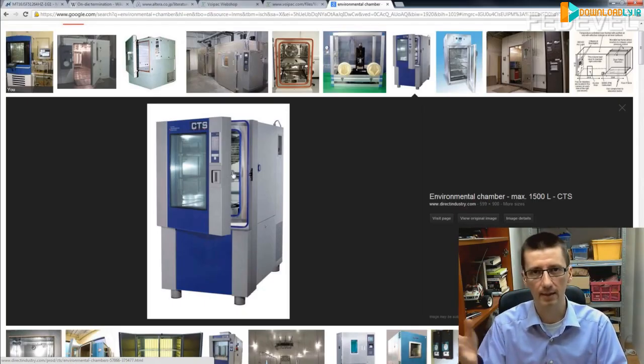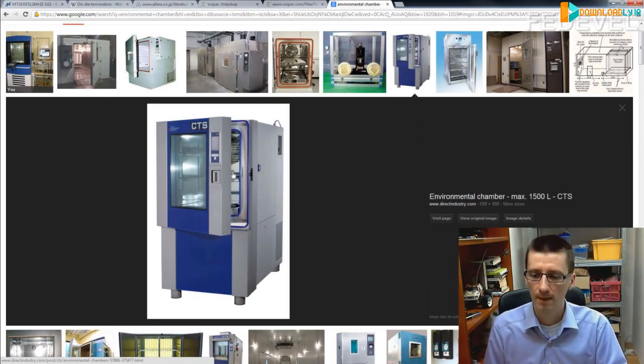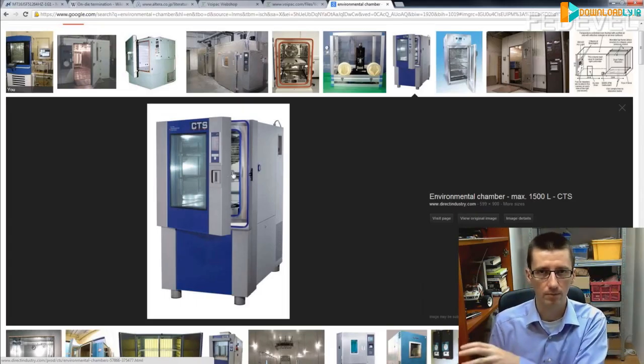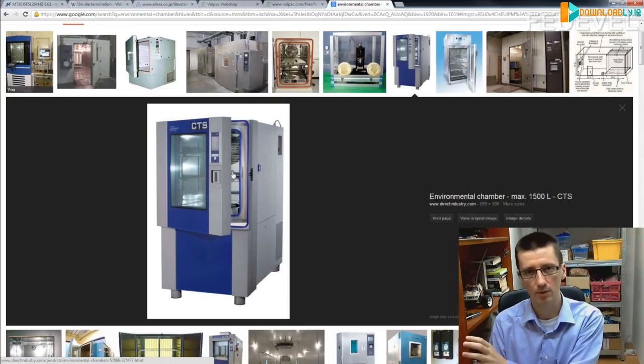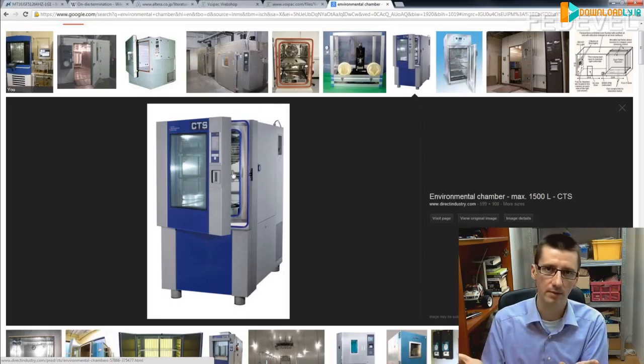For SD card, read and write, and check if it's the same. For hard drive, same. You got it. You need to have the production test anyway, so it's basically very similar. And don't place the hard drive or this kind of thing into the chamber. Place it outside the chamber, because then you don't know if the hard drive fails or your board fails.